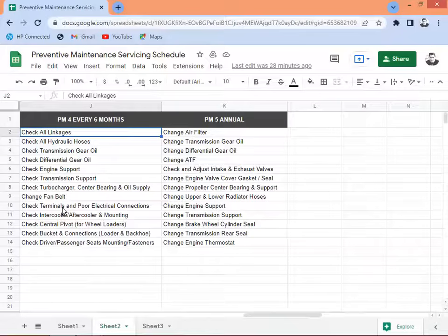The purpose of this is to have more weight of the air. In some working environments the air is thin, so the air is thinner. You make it thicker, or more weight of air, by cooling it down. So that's why some equipment use an intercooler or aftercooler, in addition to the turbocharger.